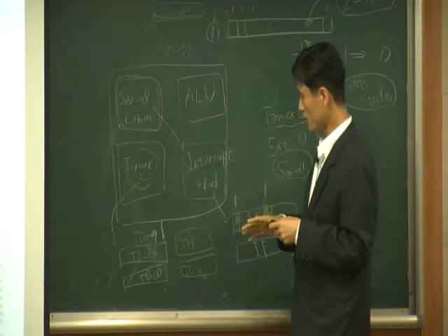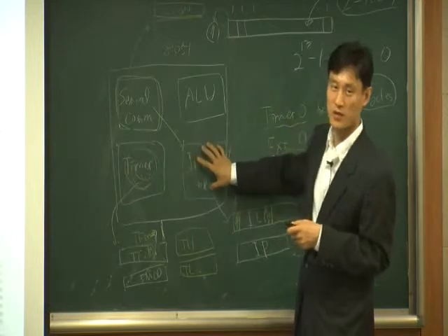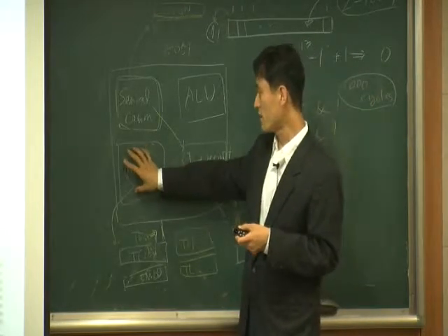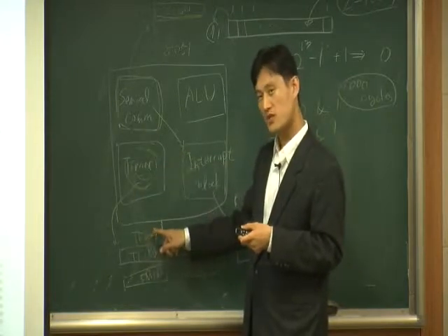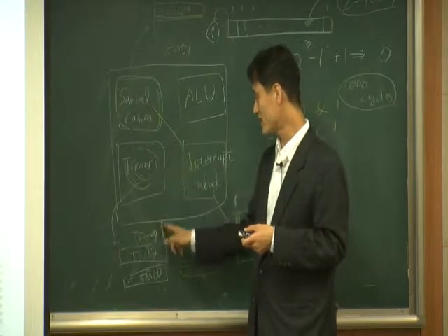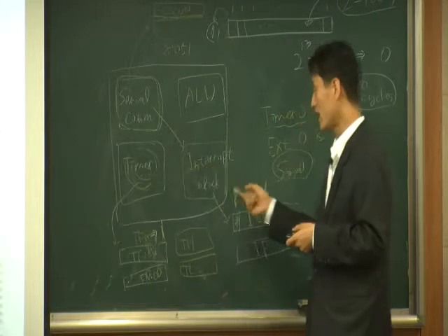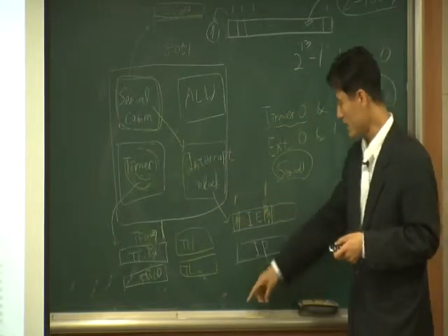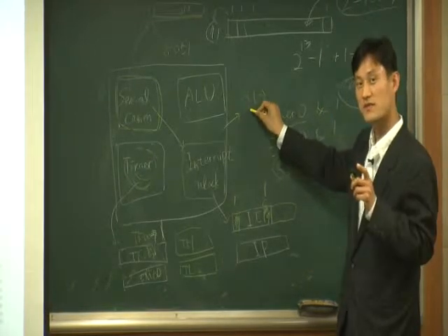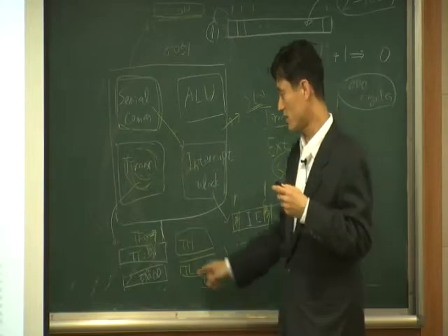But in the pure hardware technique, what you do is that you enable this block also. You are using 2 hardware blocks. So once you do that, when the timer block finishes the 1 millisecond measurement, the TF0 bit becomes 1. Then automatically this 1 means that the interrupt event occurs here. And if you enable these 2 bits, now my software will get an interrupt. So that's the difference. In that case, as software, I don't have to watch this.